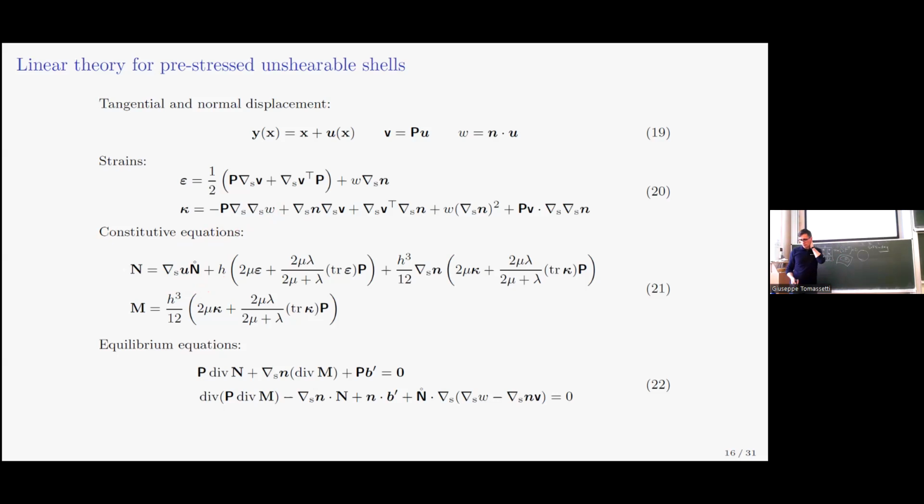And people know that when you linearize the equations of elasticity in the presence of a pre-stress, it's not true anymore that, for example, the stress is symmetric. And there is this extra term, which is essentially a geometrical term, and that eventually is responsible for the fact that the vibration properties of the eye, of the shell, depend on the internal pressure. So if you change this value, the dynamical property of the shell will change because you have changed the constitutive equations.